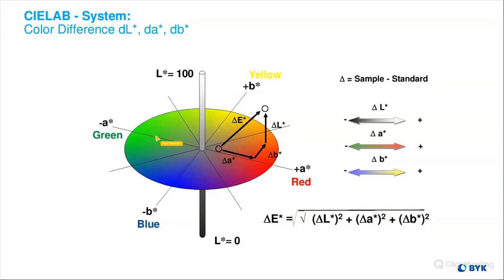And if I look at the greens and I have it set to 1.5, what will happen is, let's say I have a whole set of colors here and they're all green, and I measure a bunch of them. I can have ones that are falling outside of that 1.5 tolerance, and I'm throwing those away because they're failing numerically. But if I were to go back and look at those samples, I would find out that almost 50% of them are actually passing because I can't tell a difference between them. But numerically, because my tolerance is set low on the delta E, I'm failing all of them.